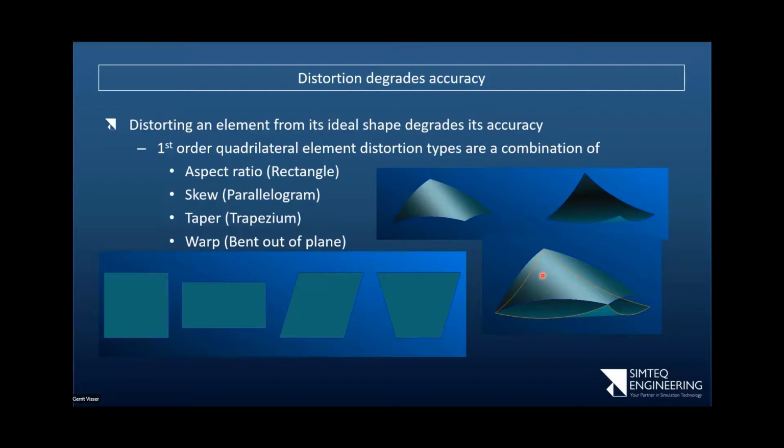Now, to see why this is an issue, if I look at this one, for example, it's very stiff if I try to bend it about that axis, but it's really easy to bend about an axis that's parallel to that length direction for this circular shape. While this one is very easy to bend about that axis, but on this angle, again, it's very stiff. Now, if you combine the two, so there is kind of halfway, we get some really weirdly distorted shape. And from that, it then ends up being stiff in two directions, which is not quite representative of reality.